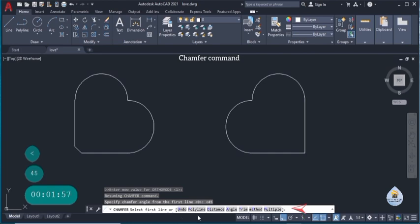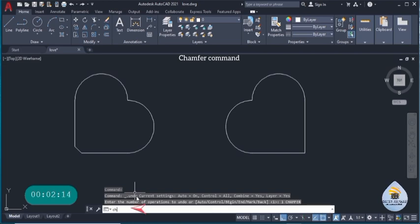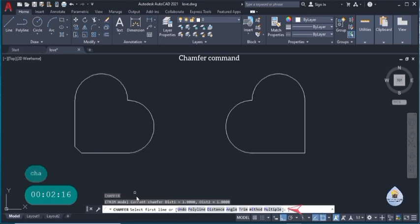So it says to select the first line. This is my first line, and this is my second line. Now this is at an angle of 45. If I redo this, I type in my chamfer again, CHA, enter. I go into angle, and it's asking me for the distance.